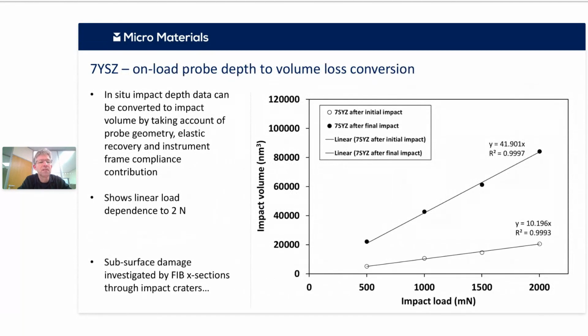And from those depths, and this is a new result again on the project, we can convert from the depth data directly to impact volume by taking account of the probe geometry, the elastic recovery in the test, and the contribution of the instrument frame compliance. And we can subtract all of that out and convert to impact volume.